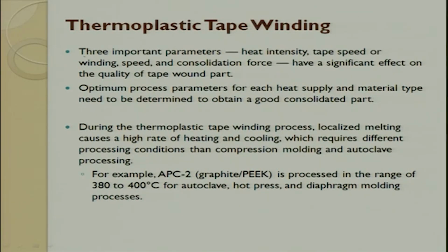So the other three important parameters are heat intensity, tape speed or the winding speed, and consolidation force. These are the three important parameters: heat intensity, tape speed and consolidation force. These three parameters have to be optimized such that you get the best out of this process.